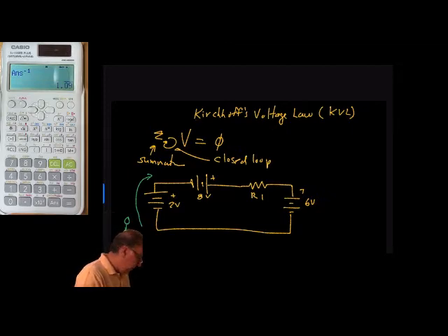So now we're going to add up the voltages around the loop, starting right here in a clockwise direction using Kirchhoff's voltage law. So we'll start here, and so this battery will become a -2, and then -8, plus VR1. So we want to know the voltage across VR1 in this case. Plus 6 equals 0. Solving for VR1 equals 4 volts DC.